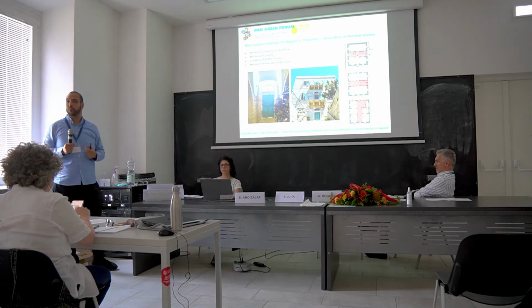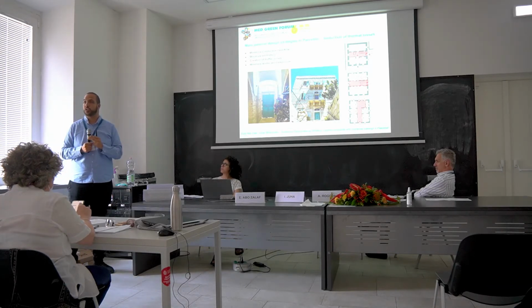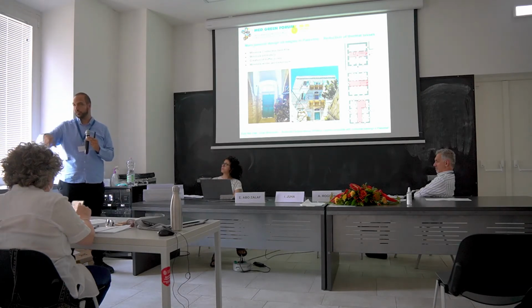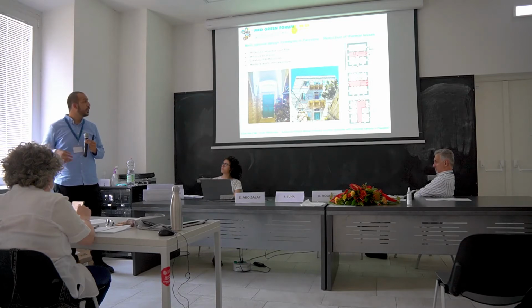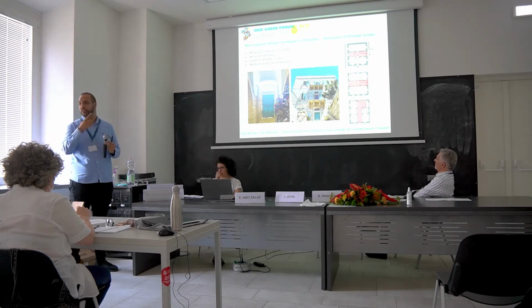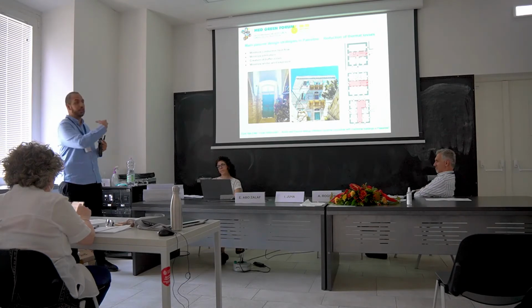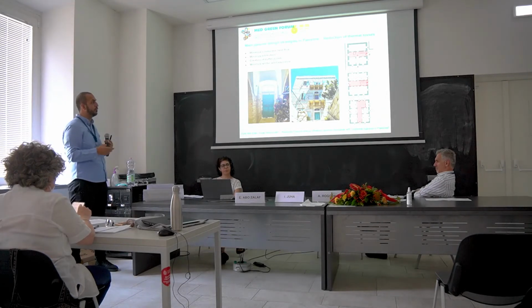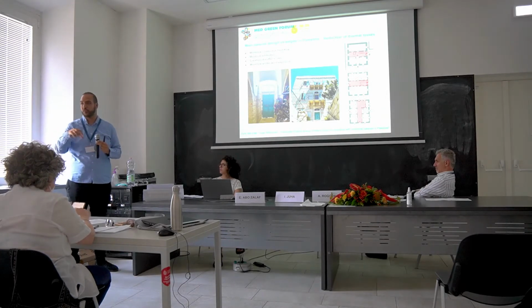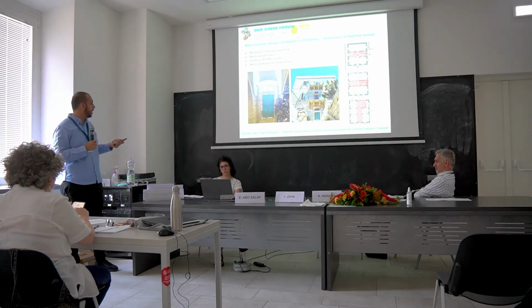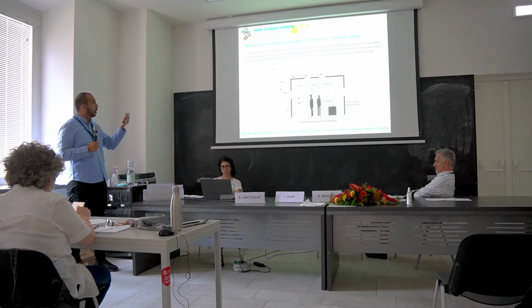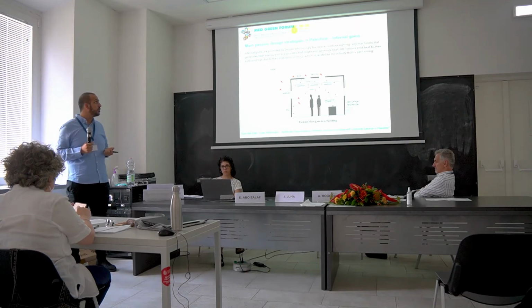the building. We always have something called the Liwan, which is the public space in the building with the stairs. It's good for ventilation, the stack ventilation I mentioned before, and it works as a buffer zone because the main doors are always in this area. Also, about the internal gains.